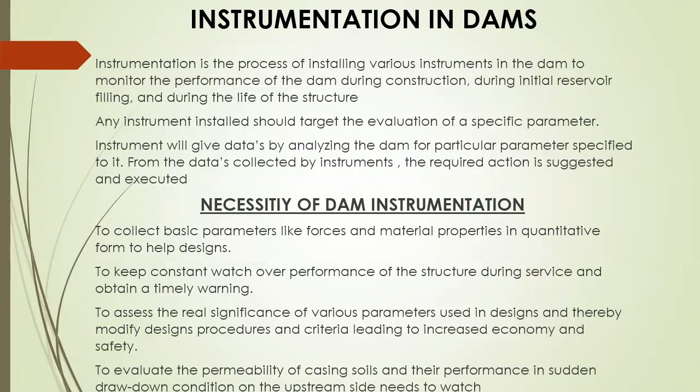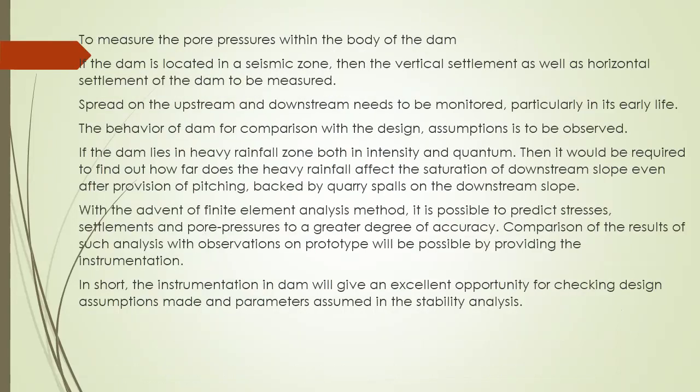On the upstream side, it needs to be watched, to measure the pore pressures within the body of the dam. If the dam is located in a seismic zone, then the vertical settlement as well as horizontal settlement of the dam is to be measured. Spread on the upstream and downstream needs to be monitored, particularly in its early life.